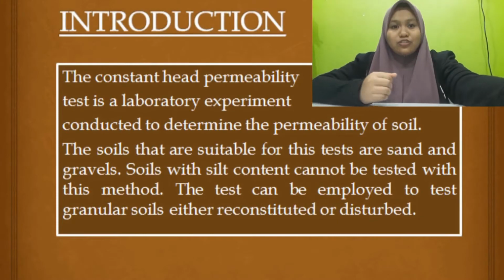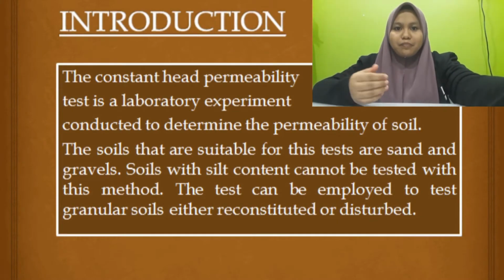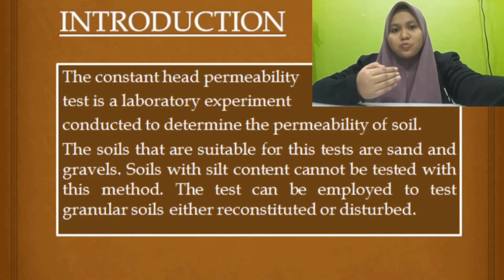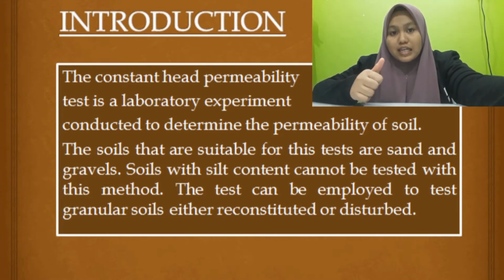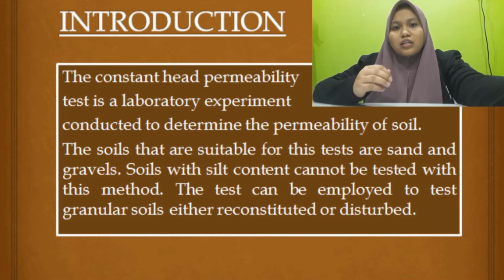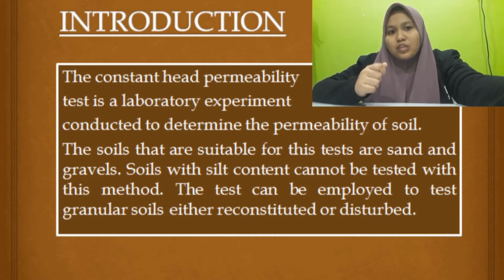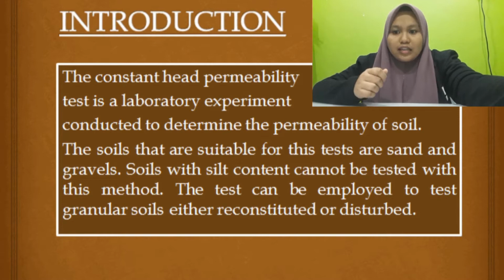Okay, let's start with the introductions. The constant head permeability test is a laboratory experiment conducted to determine the permeability of soil. The soils suitable for this experiment are sands and gravels. Soils with silt content cannot be tested using this method. The constant head permeability test can also be employed to test granular soils, either reconstructed or disturbed.